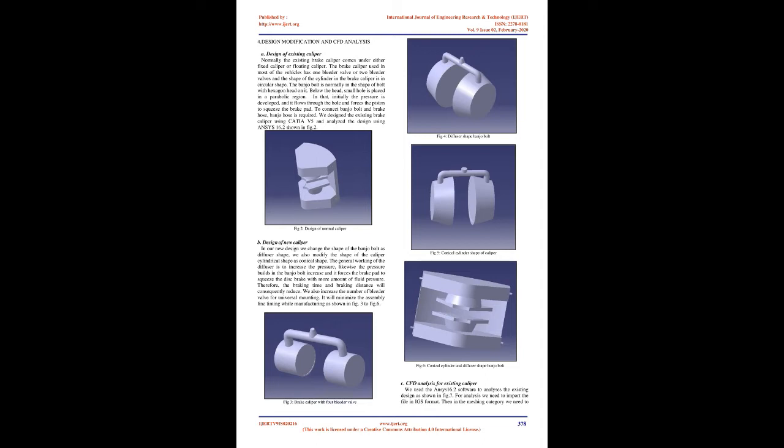Aluminium can also be used for the manufacturing of caliper considering its lower weight, but the modulus of elasticity in this case is less, 72 to 80 GPa. Also, metal matrix composites, MMCs, with base material as aluminium or beryllium, reinforced with ceramic fibers which are aligned in the proper direction to obtain required strength and stiffness along that particular direction. These MMCs have a modulus of elasticity of about 180 GPa. Pistons can be made of aluminium alloys. Its properties are shown in Table 1.